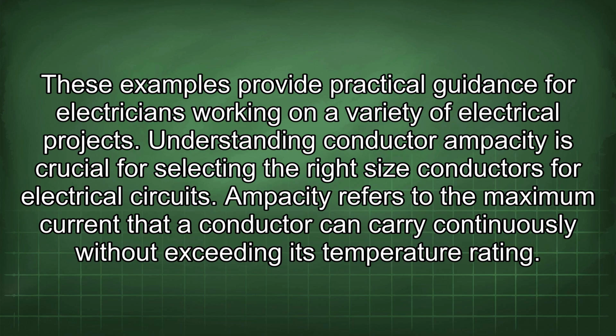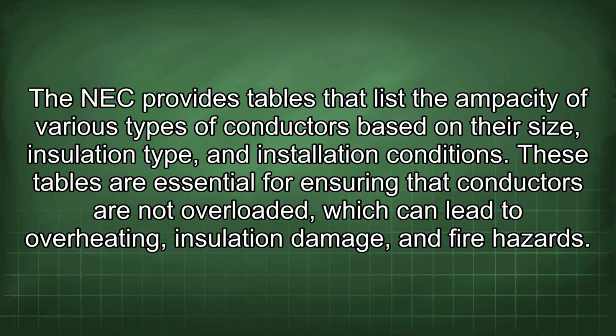Understanding conductor ampacity is crucial for selecting the right size conductors for electrical circuits. Ampacity refers to the maximum current that a conductor can carry continuously without exceeding its temperature rating. The NEC provides tables that list the ampacity of various types of conductors based on their size, insulation type, and insulation conditions. These tables are essential for ensuring that conductors are not overloaded, which can lead to overheating, insulation damage,